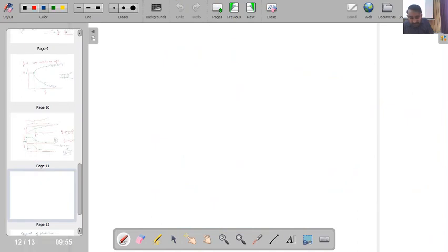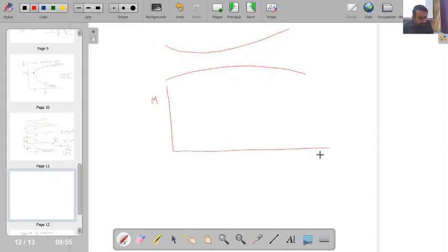Okay, so let's consider that once again the similar nozzle I am having, and I need to plot, say, variation of Mach number as function of x. Similarly, I need to plot variation of pressure as function of x, or I can call it as, say, P by P naught. Now this is the minimum area, so this is the point where my A by A star is equal to 1.